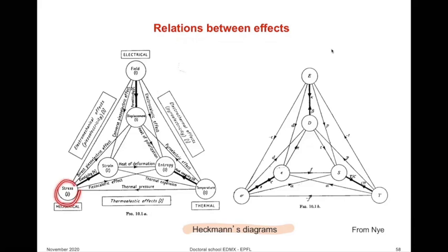So here we have a stress, temperature, and field, and here we have an effect that connects variables of the same nature. So these are electric, these are mechanical, and these are thermal: entropy, temperature, strain, stress, field, displacement. And then these cross terms are the ones that are giving us coupling of electrical and mechanical, thermal and electrical, and mechanical and thermal variables.